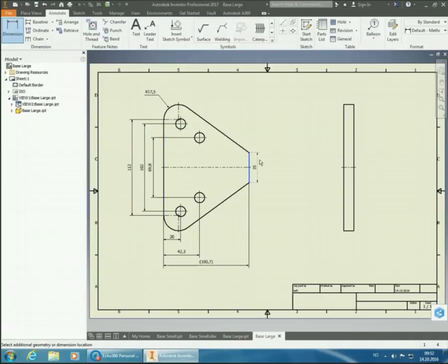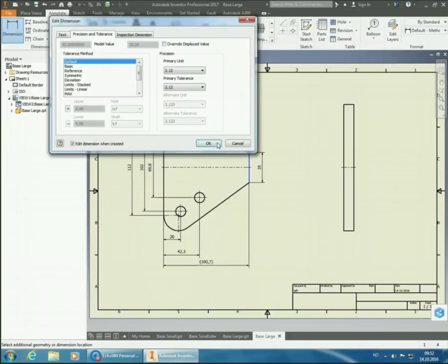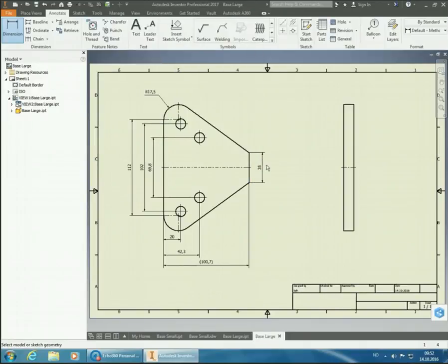Because our next dimension will be the length on this side. So we've got this 35 length there, which means that the total length of this plate is going to be controlled by the fact that we have 102 millimeters between the center points of our fillets, and we have a 17.5 millimeter radius on the rounded edge here. And then we go over in a tangent to a straight line that's going to hit this 35 millimeter line.